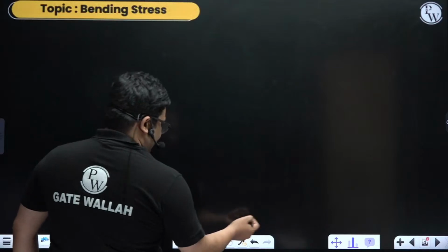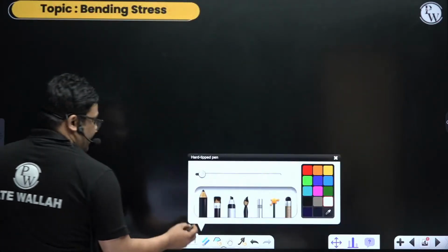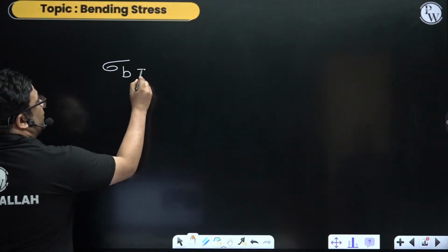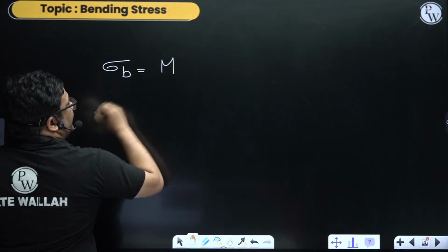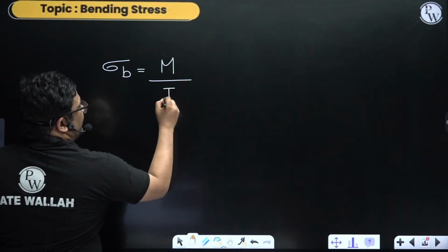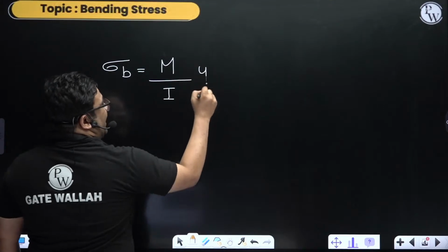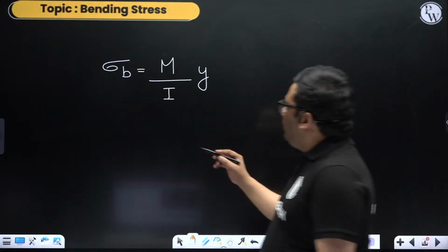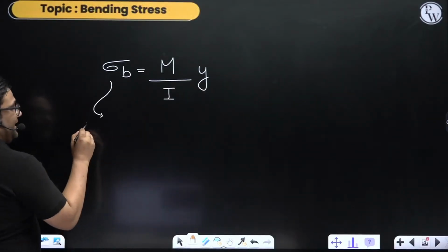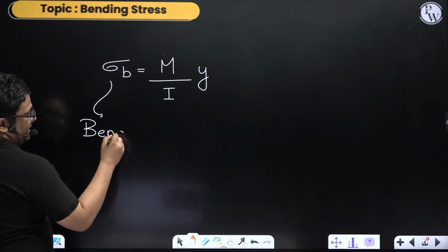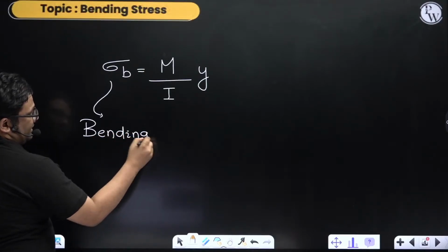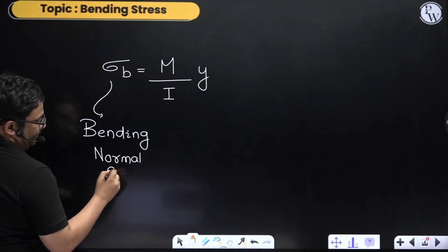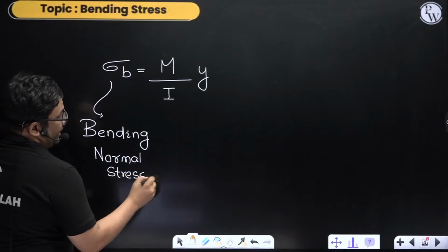What is the bending stress equation? Bending stress is equal to the bending moment divided by moment of inertia, into y. Now what is this y, we will see. This is your bending stress, and bending stress is a normal stress, so we'll call this bending normal stress.